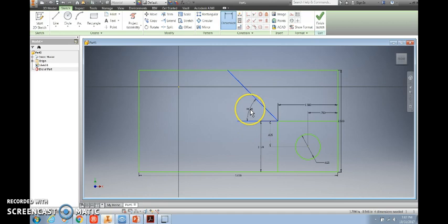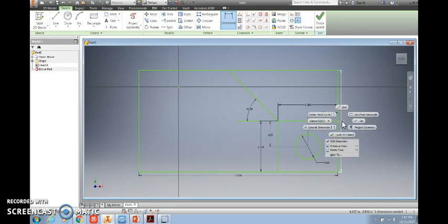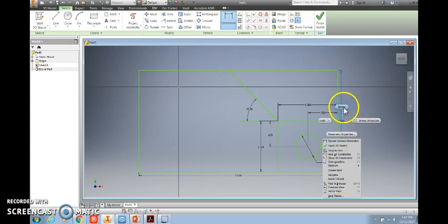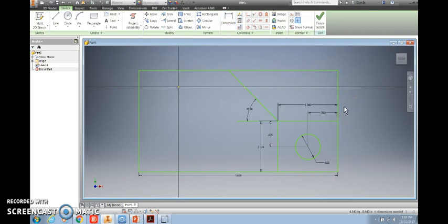And notice now I'm dimensioning with degrees. So I'll click, and now I want to set this right at 45 degrees, so I'll type 45 and enter. Now I have the line drawn at 45 degrees. I want to trim away a couple of things that I don't need, so I'm going to remove this dimension of 2.5 inches. And right click on it and delete.